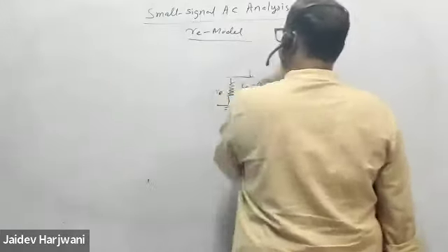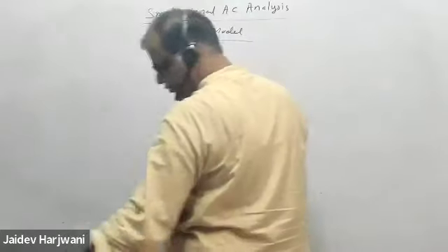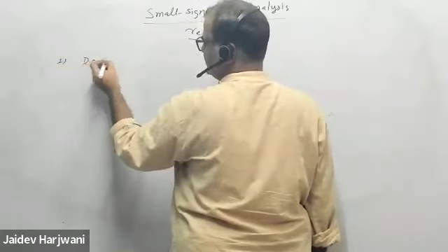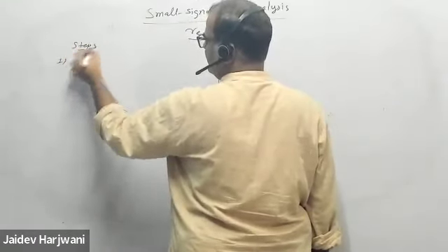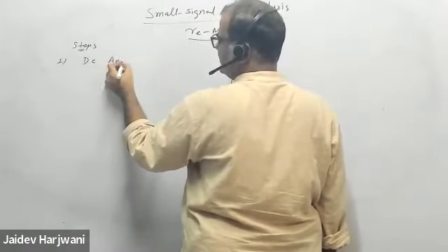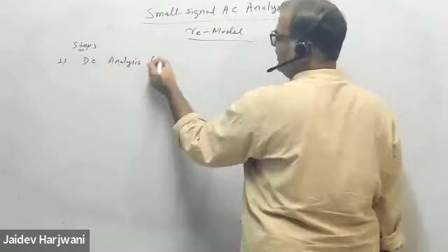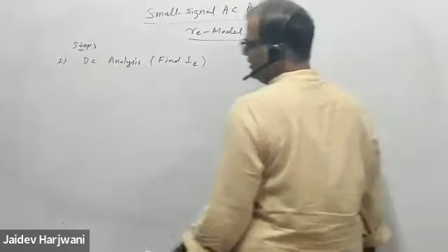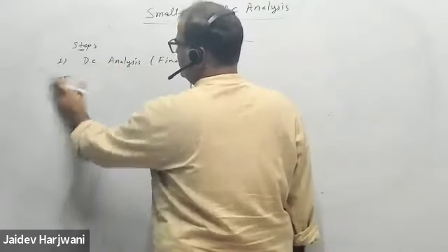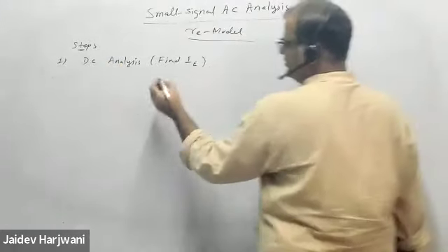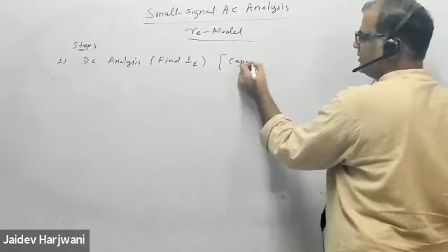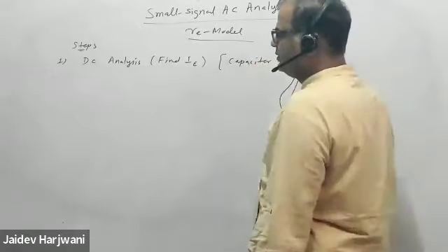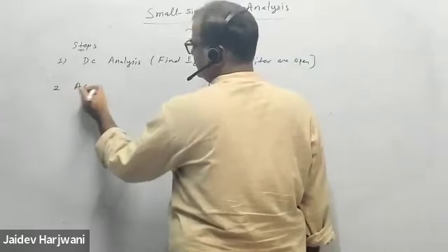So what is the idea? If you want to do the RE model, number one, you have to do DC analysis. As I told, first is DC analysis, and find the IE value. In DC analysis, capacitors are open.